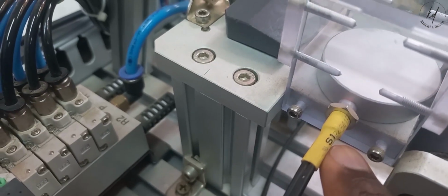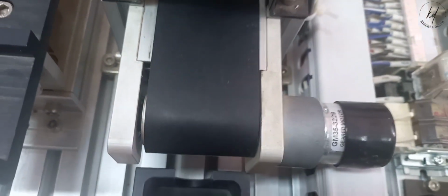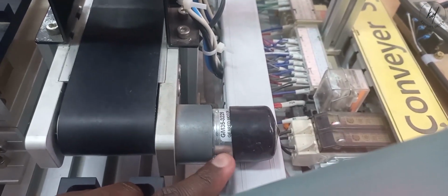Here S1 is sensor 1, known as the magazine sensor, which detects whether any object is fed to the box or not. At this moment it detects a circular metal. This is the storage where the product is to be removed, and there is a rolling belt type conveyor in between the supply emitter box and the item remover box, which is driven by this geared motor, as you can see.